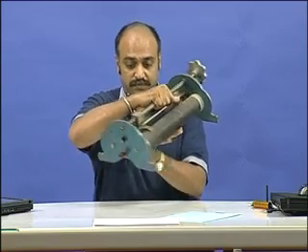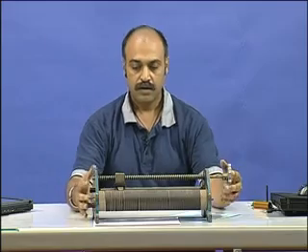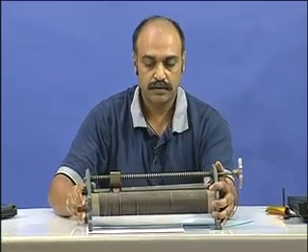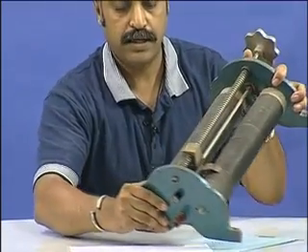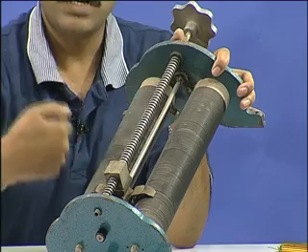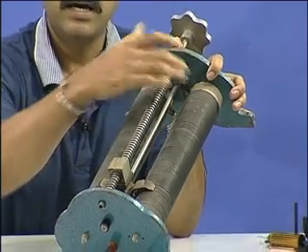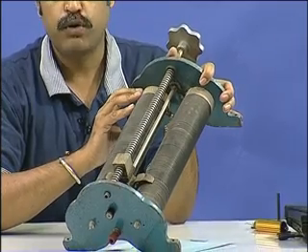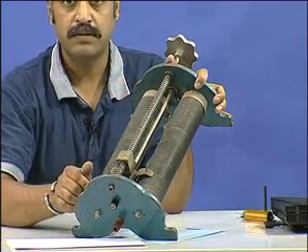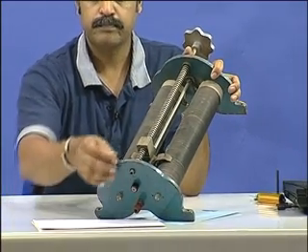It is pretty heavy. Okay, so let me place it here. You see that there are 2 cylinders. Are you able to see? I will hold it like that. There are 2 cylinders composed of wire wound wires. They are connected in parallel such that they can handle higher current and therefore more dissipation. These can handle something like 25 amps and they are 2 ohms, which means something like 1250 watts.